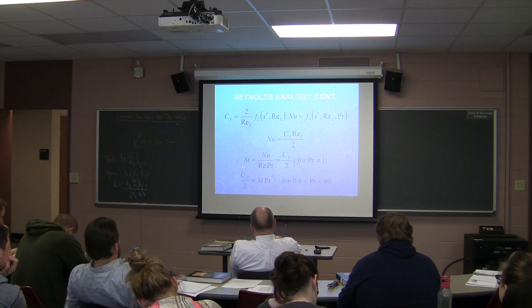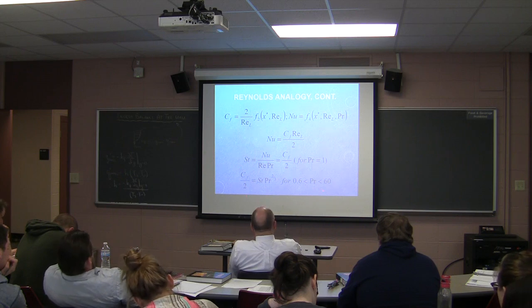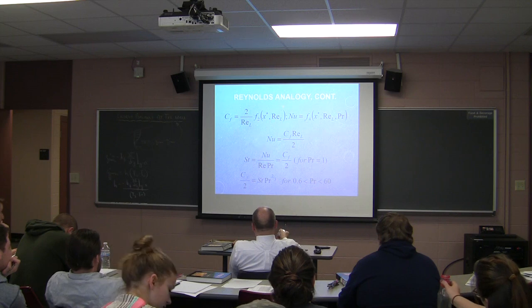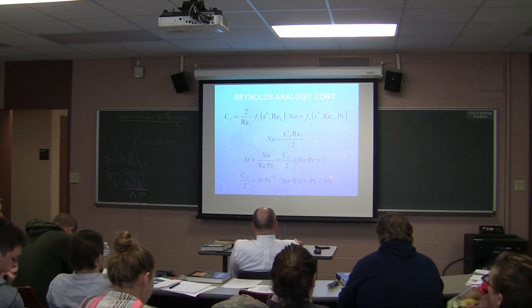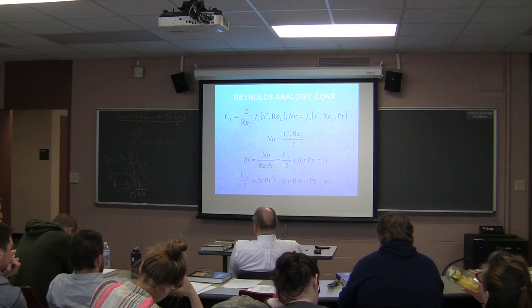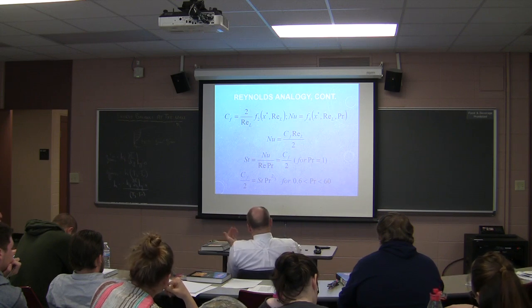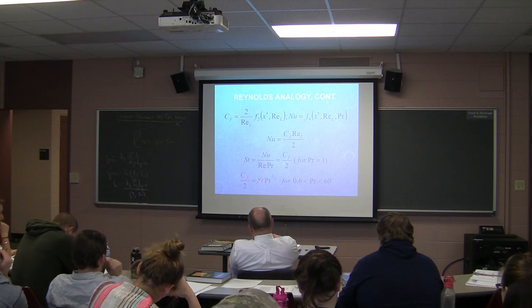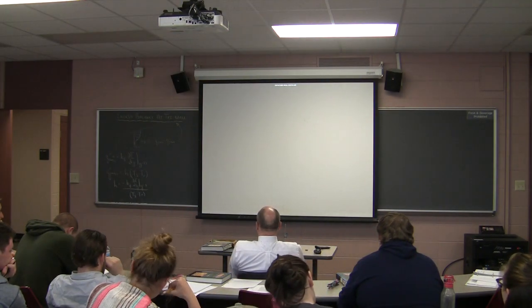And this is what they know as the Chilton-Colburn equation, which is an improvement on the Reynolds analogy for a greater range of Prandtl numbers. So now for a range of Prandtl numbers between 0.6 and 60, which takes up essentially all gases and liquids other than metals, you can relate the coefficient of friction to the Stanton number and the Prandtl number. And that's what Chilton-Colburn did.